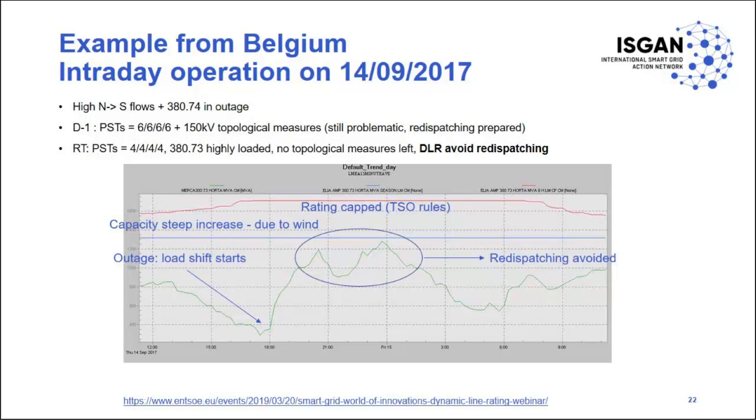However, they realized that this would not be enough to get rid of the potential N-1 security violation. Therefore, they decided to make some topological arrangements in the 150 kV subtransmission grid, also to try to redirect away some of the power flows. Even with all the effort by the grid operator to solve the congestion using his own assets, it could not get rid of the potential N-1 security threat.